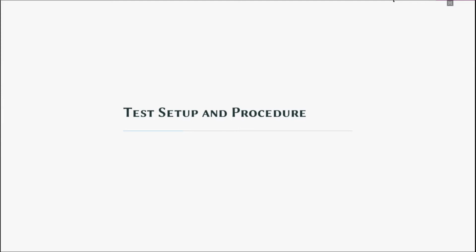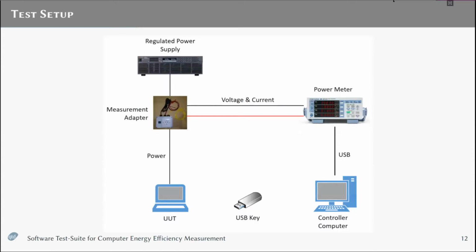Okay, so I will briefly explain the test setup through this slide. As you can see, it's relatively simple. You don't need much equipment. What you need, and very important, is a regulated power supply. We want to have a stable voltage as an input to our unit under test. This is why it is important that the power supply is regulated, but I'm pretty sure that in your labs, you already have regulated power supplies.